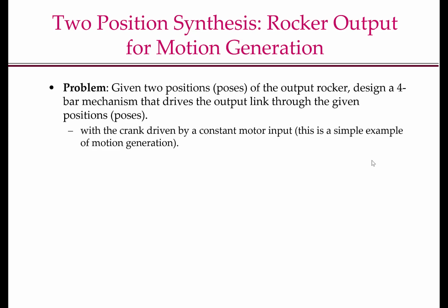We had seen two possible metrics for evaluating a design. The first one was the Grashof condition. We wanted to check whether the mechanism was Grashof or not. This is because we wanted a crank rocker mechanism, and if the mechanism was non-Grashof, then there would not be any crank. The second check was about transmission angles. At this point, the key high-level bit that I want you to take away from the procedures is that design involves choices and design is iterative. You may have to do multiple iterations before you come up with a satisfactory design.